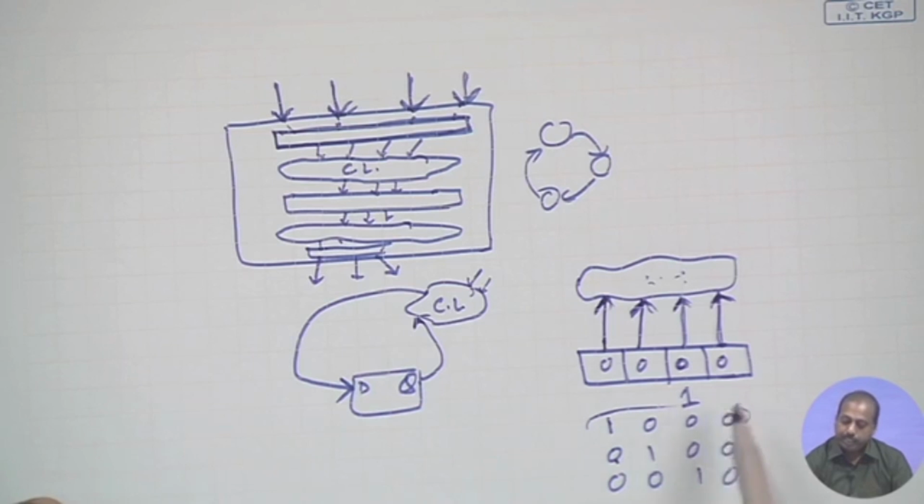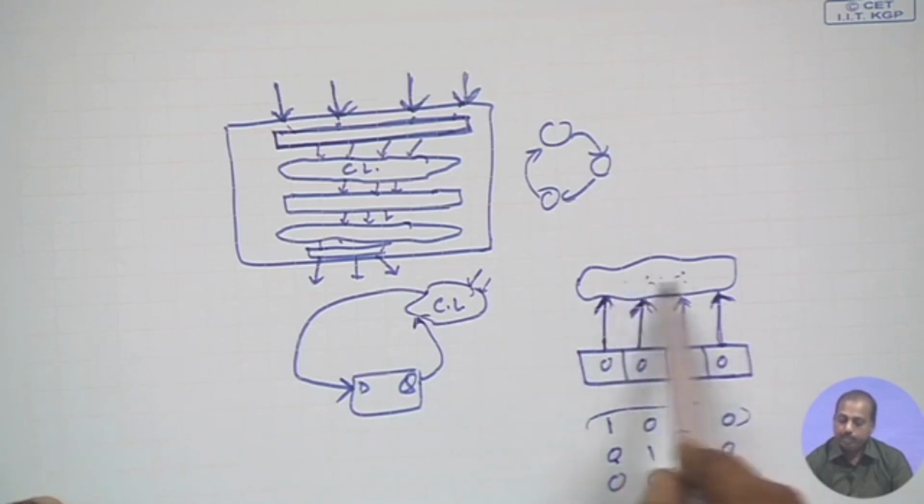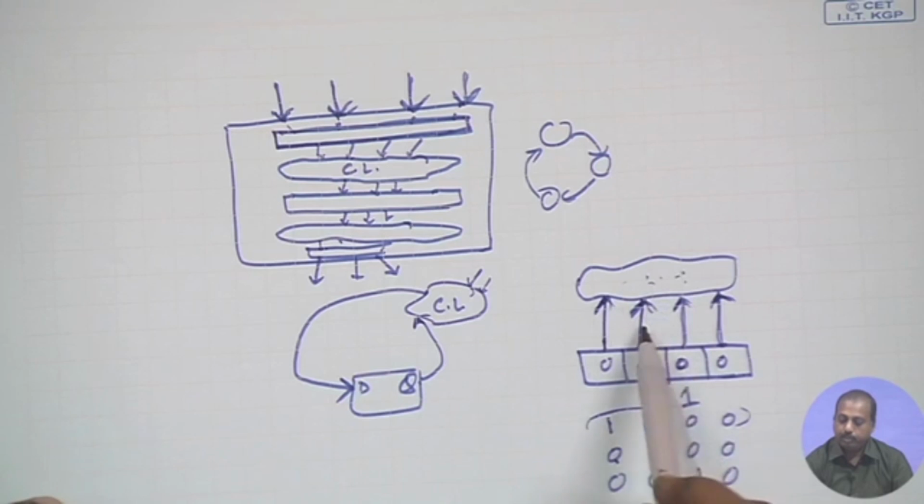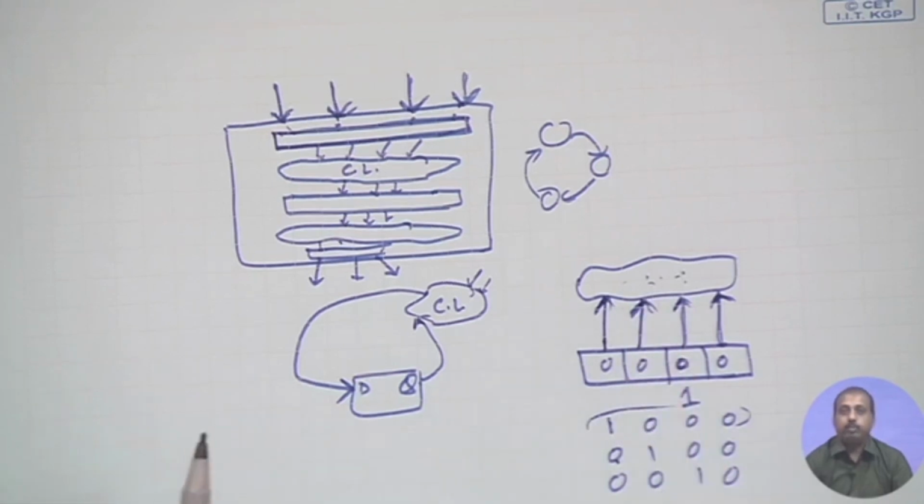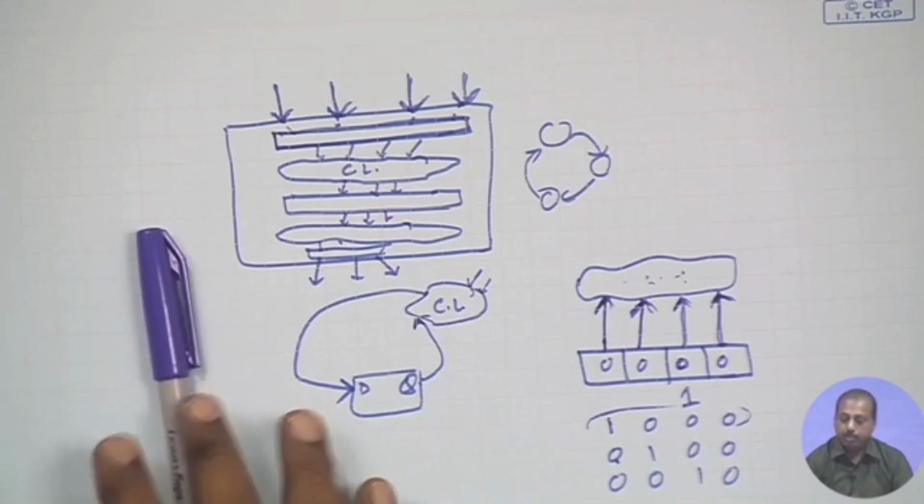This way, every time I shift a bit into this scan chain, the scan chain pattern changes, and as a result these bits will also change for the combinational logic input, and the combinational logic will do some transitions. As and when they make the transition, it will consume power. And we know that for CMOS circuits, the dynamic power is consumed only when its output changes.